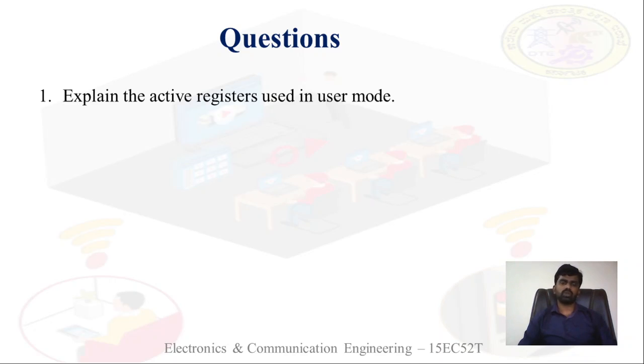Along with that, another 2 status registers are there. Which are those? Number 1, the current program status register, that is CPSR. Similarly, another one is SPSR, that is saved program status register. And we have also discussed the bit structure of CPSR. In CPSR there are 4 fields: control field, flag field, status field and extension field. So we have studied all these topics in this class.